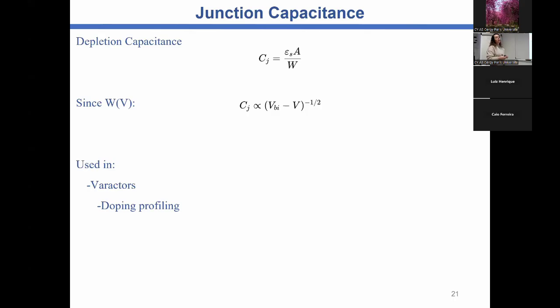If you have materials with more free sites where you can put some electrons and keep them trapped, sometimes this electron also can move, and this movement will affect the measurement that you are doing. And we can also know the capacitance of the interface by analyzing the bandwidth and the dielectric property of the material.